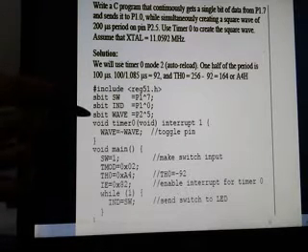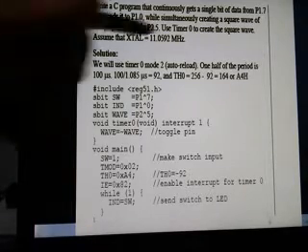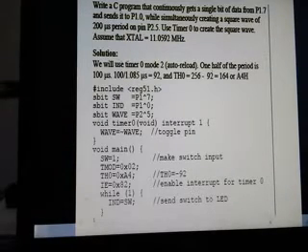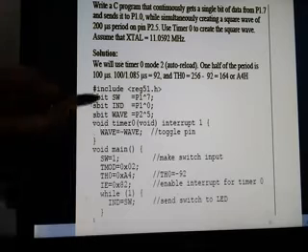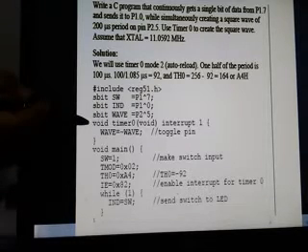Okay, one more variable is declared, as we want to generate a square wave. At which pin? We have to generate a square wave at P2.5. So P2.5 is also assigned to a variable. So that variable is given the name wave. Now observe this. This is how the subprogram is to be written. Okay, or the function is to be written in C.